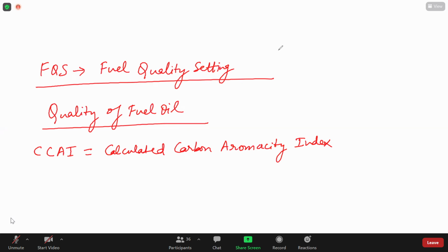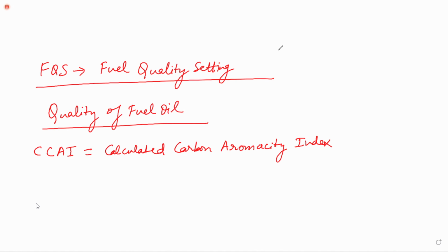Sir, since the ignition delay will be more in 850, we have to adjust the fuel injector accordingly. Not the fuel injector, like the fuel injection timing we will have to adjust. Very good. So you'll have to adjust the fuel injection timing. Which direction do I adjust the fuel injection timing?